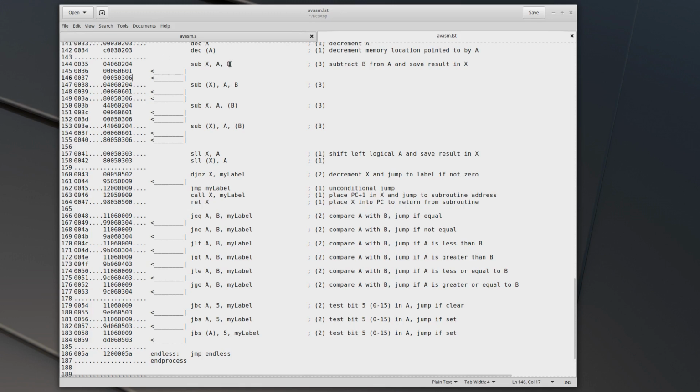So register 4 is the B register, and we are exclusive ORing it with register 2. Register 2, remember, is one of our 3 predefined registers that we put on at the start of the program. Register 0 is 0, 1 is 1 and 2 is -1, or FFFF. So what we're doing here is exclusive ORing register B with FFFF. In other words, we're inverting all of the bits in register B, and we're storing the result in register 6.